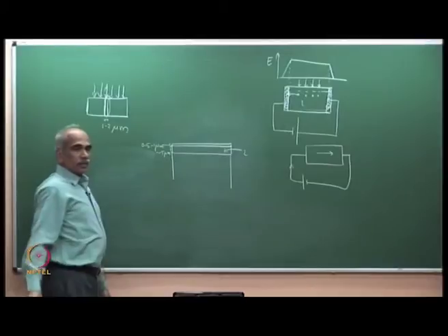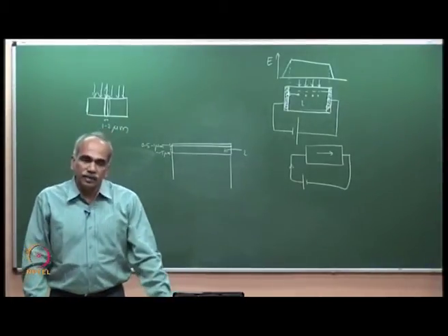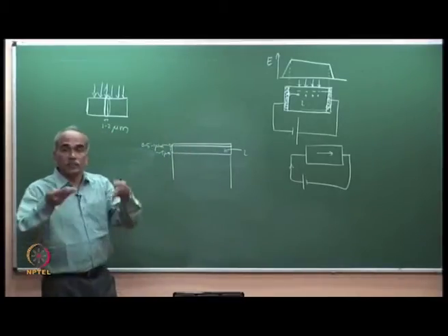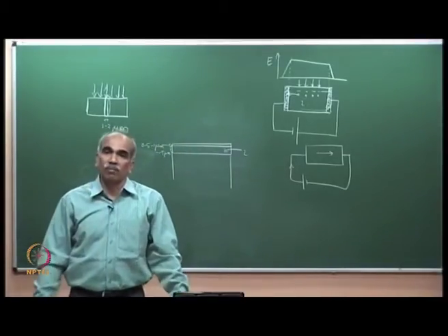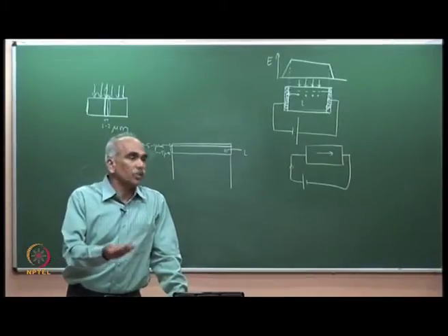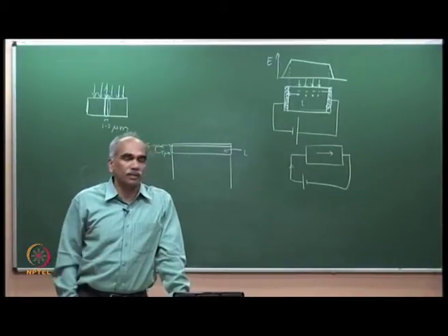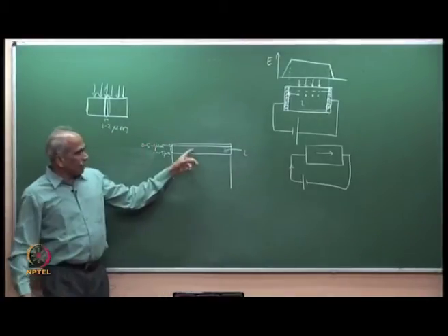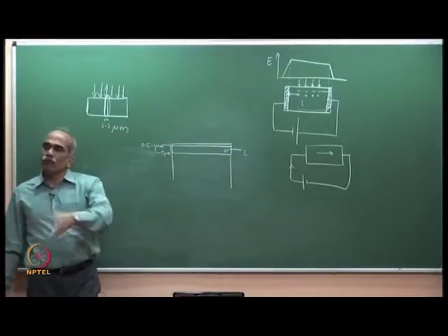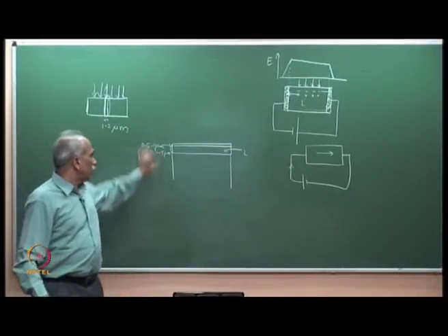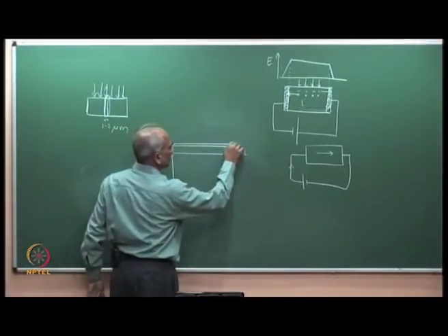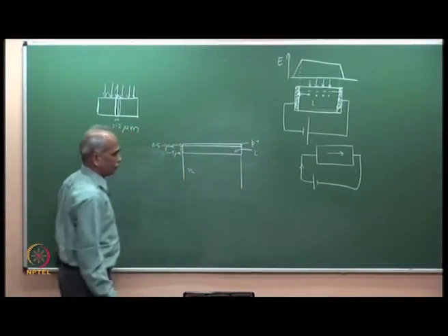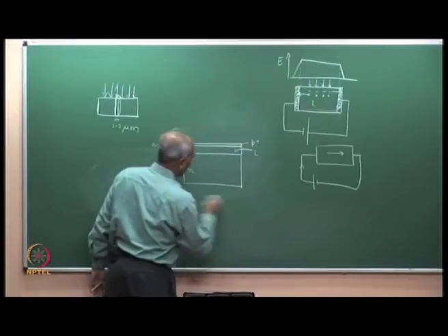If you remember in one of the earlier classes, we had calculated the thickness of the semiconductor required for 90% absorption. It was just 1 micron. 1 or 2 microns is sufficient to absorb almost 90% depending on the absorption coefficient. And therefore, typically the I region has a thickness of a few microns, several microns, and you have a P plus region here on top, and this is the I, and then this is the N region and the electrode contact.